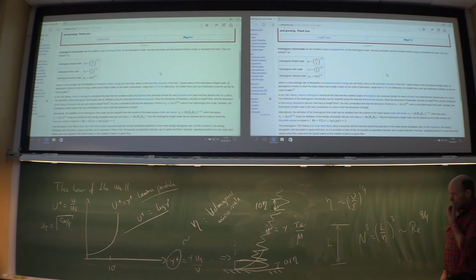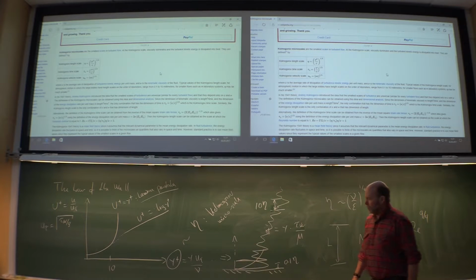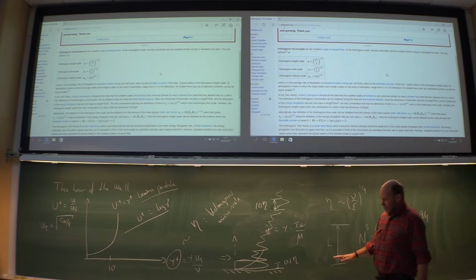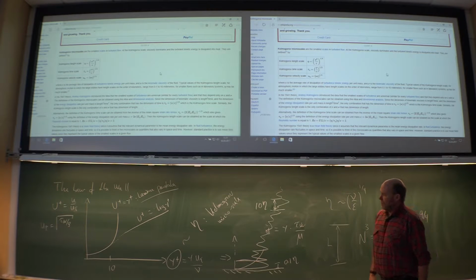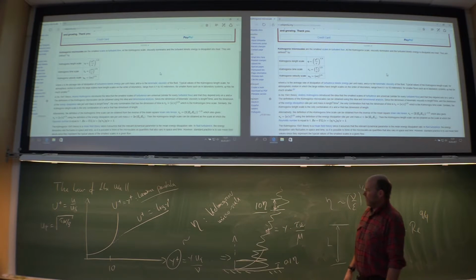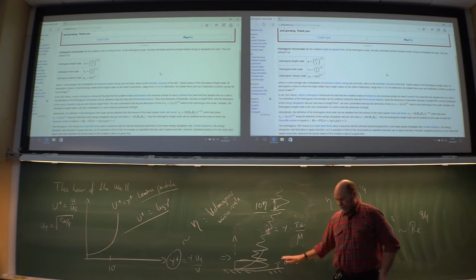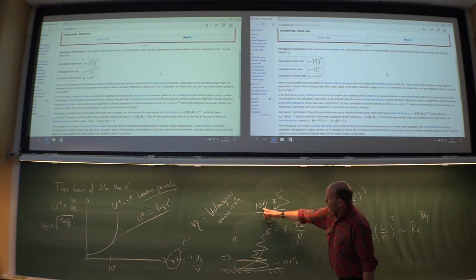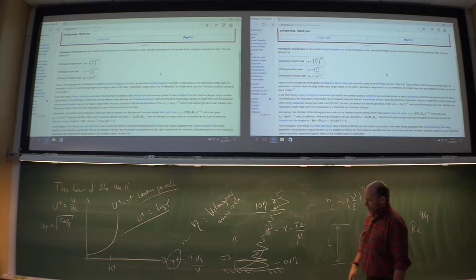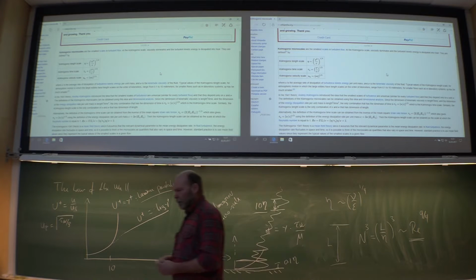Another way we can cheat is in the other dimensions. Here we have the direction perpendicular to the wall. If you look at the streamwise or the spanwise direction, then you can definitely use bigger length scales. So the cell closest to the wall is extremely thin, but it can be pretty wide. That's okay. Some 10 Kolmogorovs in both directions should be okay. But still, a very, very big number.